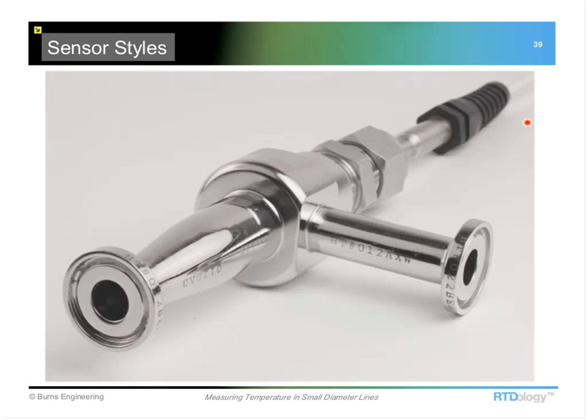These are typically designed for 100 psi or lower, for your typical pharmaceutical type applications. None of those are really ever high pressure, but depending on what kind of tubing the rest of the piping system is made from, we can match up that same material, wall thickness, whatever, and one could be designed that would work in that type of situation.